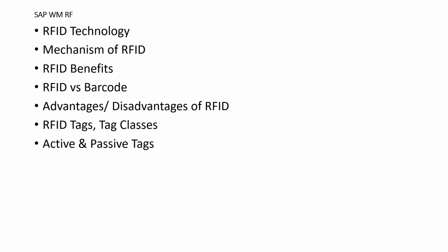Active tags are battery-powered devices that have active transmitters on board. Unlike passive tags, they generate RF energy and apply it to the antenna. So the internal power source is there. This autonomy from the reader means that they can communicate at a distance of several kilometers or more.